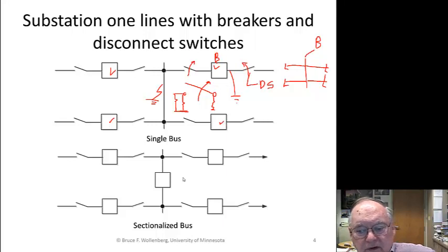This system down here, we can sectionalize the bus. If this one were opened, then we would have the lines coming into 2 buses. So if that breaker here is open, then this bus splits into 2, and it literally creates a second bus. So the software, especially in the operations centers, has to be able to take into account sectionalizing like this and opening of a bus.